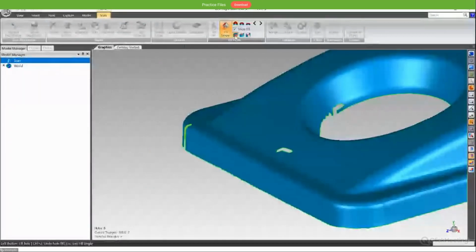Complete. So I would say these are the three modes of the hole filling function, which are complete, partial, and the bridge. Here are the filling techniques, which Geomagic calls filling techniques, and here we call fill modes.